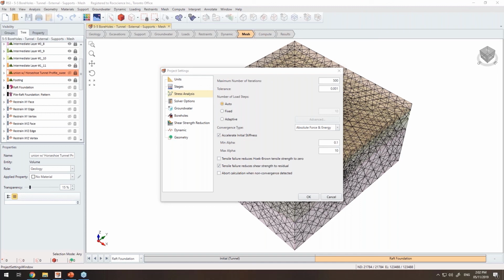Does the tunnel sequence designer do staged excavation, shotcrete, and all that? Yes. When it's going to be available, I think by the end of the month, the sequence of excavation will be done, and also with the sequence of excavation, you can stage your supports, and even the composite supports that you are defining will come as staged and defined by the tunnel sequence designer.